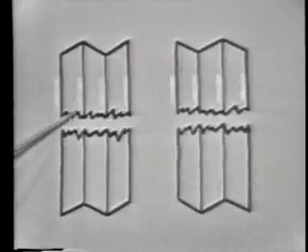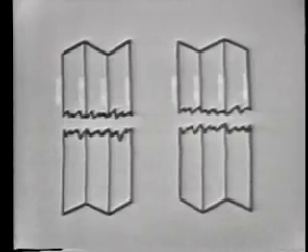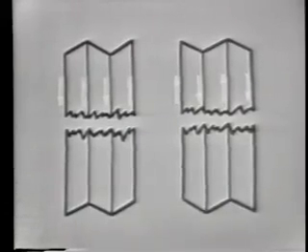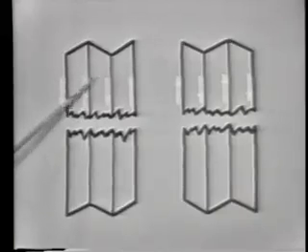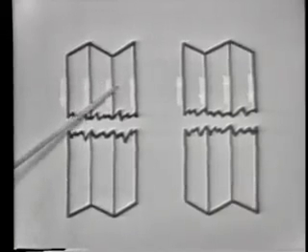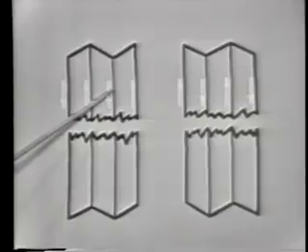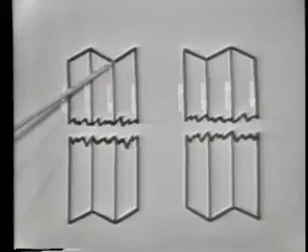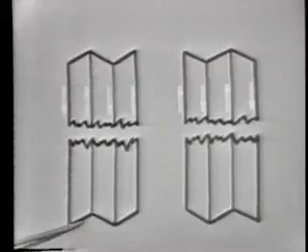Notice that the deformities are opposite for each alternation. Now, here we're representing the crystal when it's made to oscillate in the third overtone. Let's notice that the crystal breaks up into 3 layers when it's oscillating at the third overtone. This is representing the deformed layers to produce one alternation.